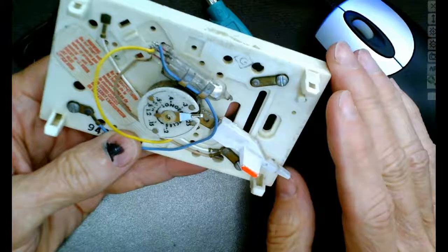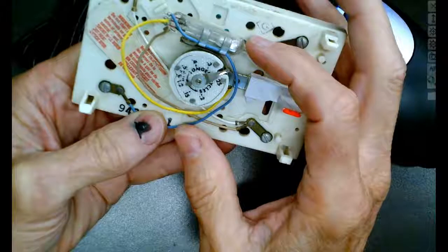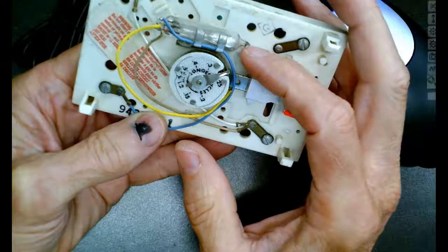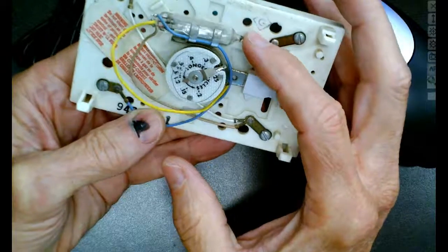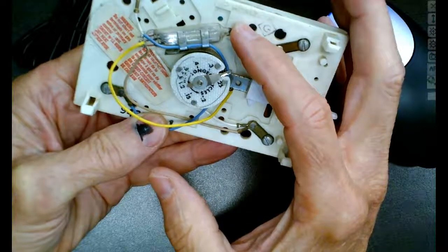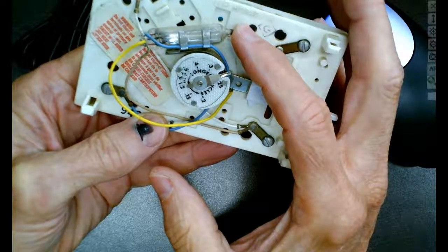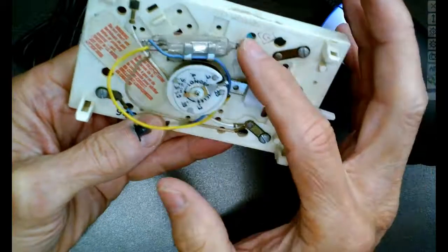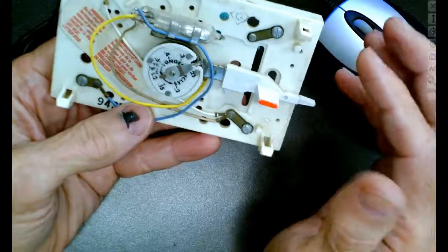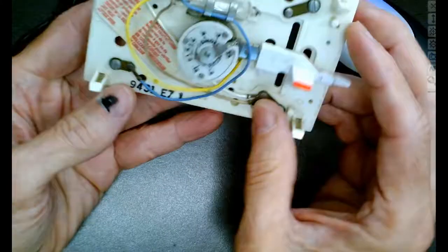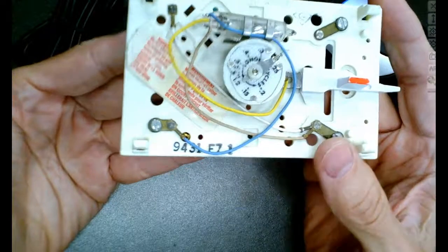And what you would do is you would set a temperature over here, and then when it heated up, it would move in one direction, and when it cooled down, it would move the other way. And you can actually see the mercury in there that would fall back and make a contact. When it made contact, it would turn your air conditioner on or off, depending on what you were doing. So this was in fact for heaters. It was a long time before we had central air conditioning systems. So these are the type of thermostats that we had for years. And some old houses you get into might still have one of these thermostats in there.